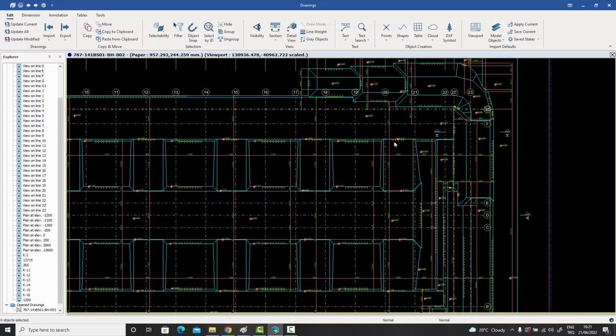And since we are talking about formworks, the main thing which we need to remember is that the formwork object is not a model object, it's a drawing side object. It is created by merging elements from the model, and as to which elements are merged together, that will depend on their usage grouping and also on the variable which we discussed called formwork group.